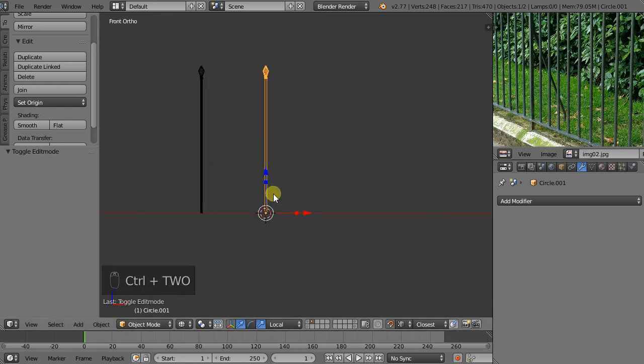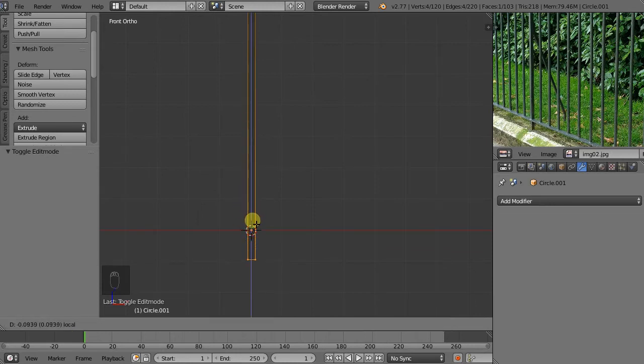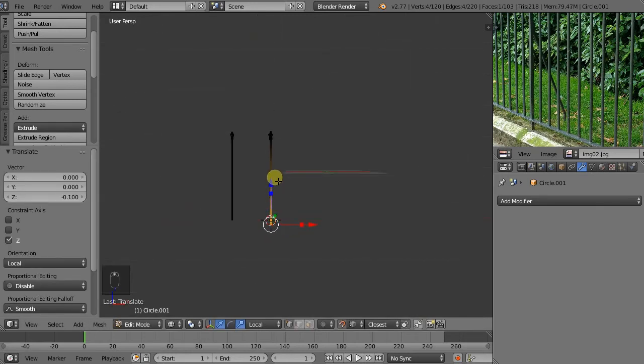So if I go to the front view, edit mode, let's move these about 10 centimeters down. 0.1. So I type 0.1 with the keyboard and then press the minus key to toggle whether it's in the positive or the negative direction, and we can press the minus key at any point. It doesn't need to be exactly in the beginning. Okay, so now we have it where we want it. So now we use this bottom face to actually recreate this object here.